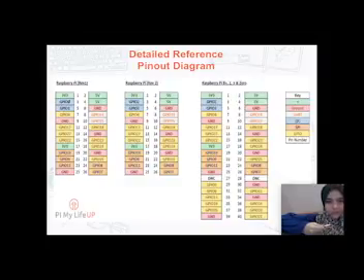If you can see on pins 27 and 28, there's DNC, which is do not connect, and there's two other pins, which is power pins that pull power directly from the Raspberry Pi, and GND, which is normal ground pins.